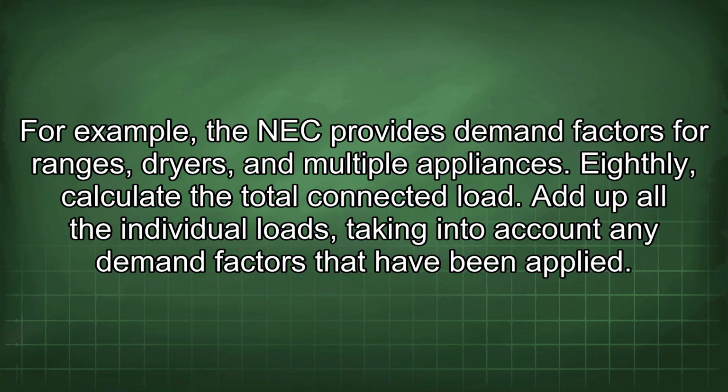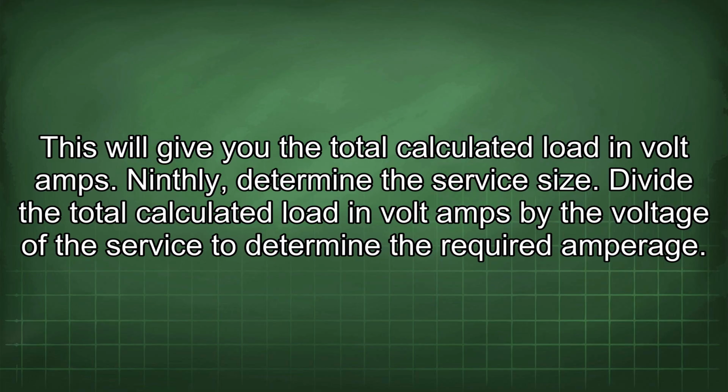Eighthly, calculate the total connected load. Add up all the individual loads, taking into account any demand factors that have been applied. This will give you the total calculated load in volt amps.